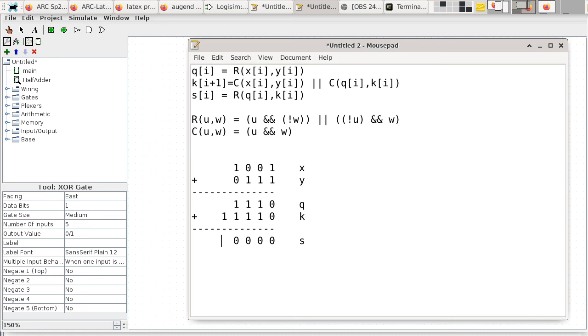All right. The idea of presenting this picture is because I want you to see how we use these 2 bits to come up with this bit, which is a half adder. That is half adding. And then we take these 2 bits to come up with this bit. That is also the same mechanism. It's also half adding. So we need the half adder, we use it twice, and then we need another thing to figure out the carry bits.